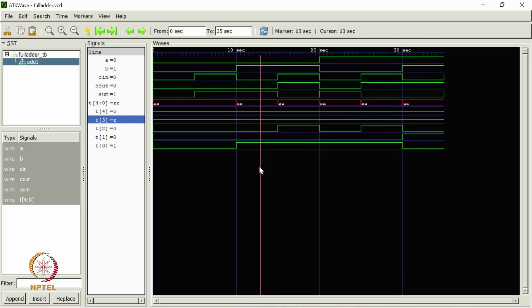This high impedance state can also be handled by driving the node using a very weak pull up network or an external pull up. This is possible in certain circuits. We put certain weak pull up networks to avoid this high impedance state. This state is not desirable because now the output is not driven by any network, not pull up or pull down.